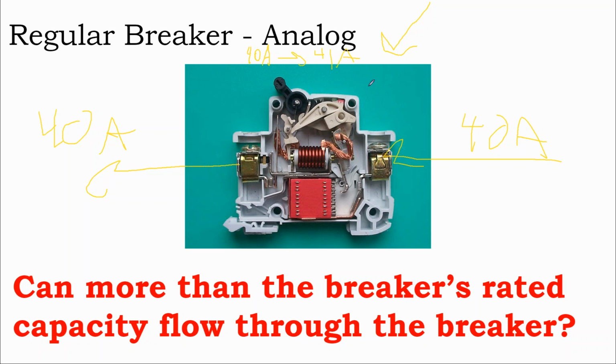this breaker should trip. So how does it do that actually? Well, it basically uses the heat from the wire. This coil expands and contracts with heat, and that expansion drives a lever that literally opens up the switch. So it's heat driven, based on having too much current flowing through that conductor. It's just an overcurrent protection device. And so we have breakers to make sure that if our devices are malfunctioning in a way that they're pulling so much power through that it would cause the cables themselves to start burning up, then the breaker trips.